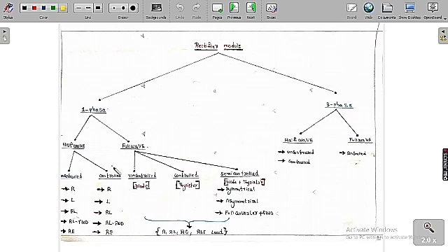Similarly, for the controlled, we are going to keep the thyristor. With the help of the thyristor, it is controlled. So here we are going to vary the loads of R, L, RL, RL with freewheeling diode and RE load. With all these loads, we are going to see the variation of each and every parameter in the circuit.